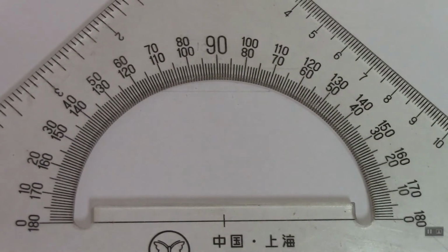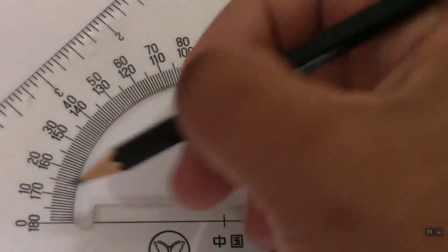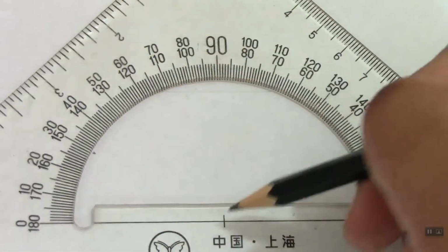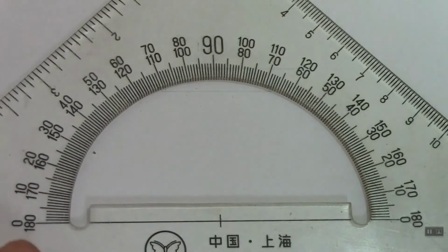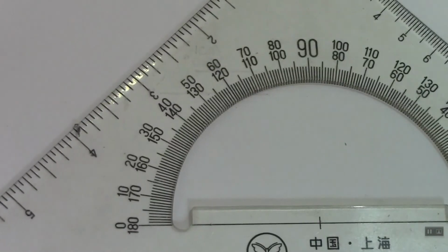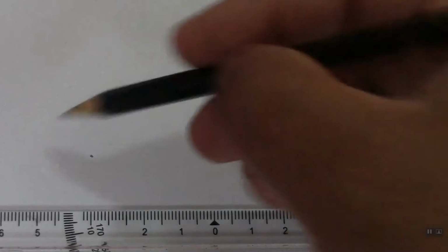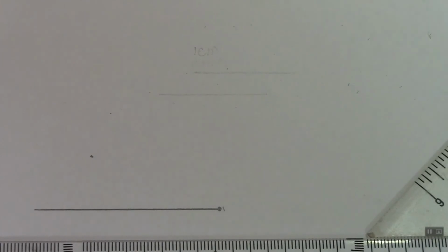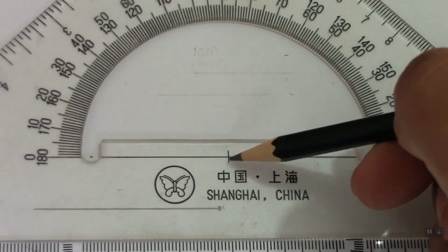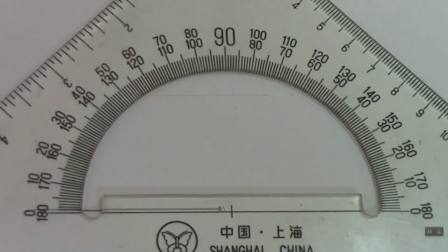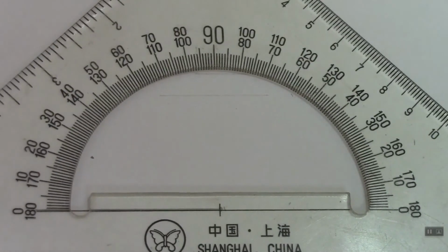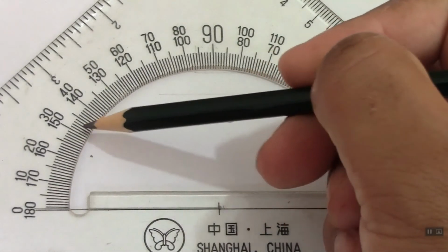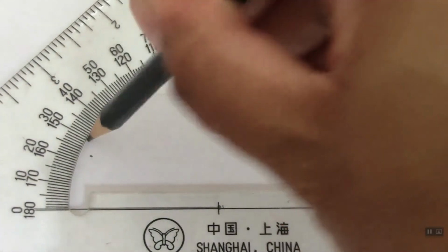Okay, if I ask you to measure 35 degrees, for example, let's say 30 degrees, so you count from 0 here to 30, so you can put a remark here. From the center to here, for example, I have to draw a line of, let's say, 30 degrees. So first of all, I draw a line. This is starting from here. I must draw a line making 30 degrees. So this point here is the center of the protractor. So you put the center on the line here, okay, on the end of the line. Then from 0 to 30, so this line is 30 degrees, I put a remark here.